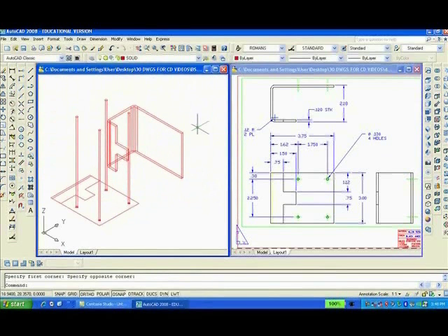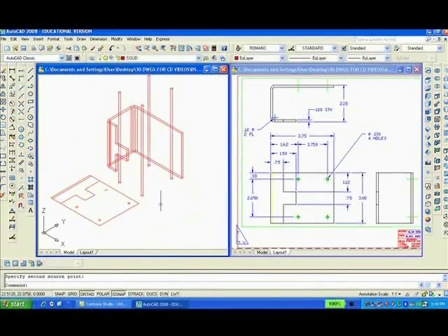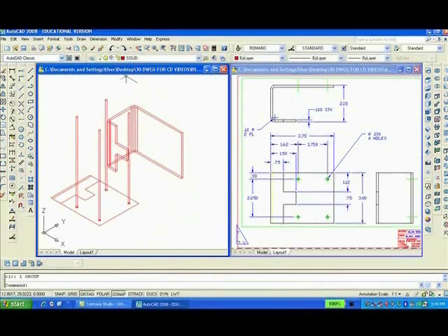Now the next thing to do is use another command, ALIGN. It's called align. I really want to align these 4 holes or cylinders, whatever you want to call them. And I have to pick some points. The first point I'll pick, I want that to go here. Spacebar. Undo. Try it again. ALIGN. Pick the 4 cylinders. I hit enter and I shouldn't have.